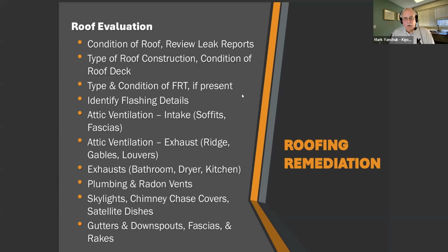By code, all exhausts have to be vented directly to the outdoors. A lot of times we go into roofs and we see bathroom exhausts just venting into the attic, or they're venting right over the soffit, or they're combined into a plenum box, and then there might be two or three bathroom exhausts combined into one plenum box, and then there's only one penetration through the roof.